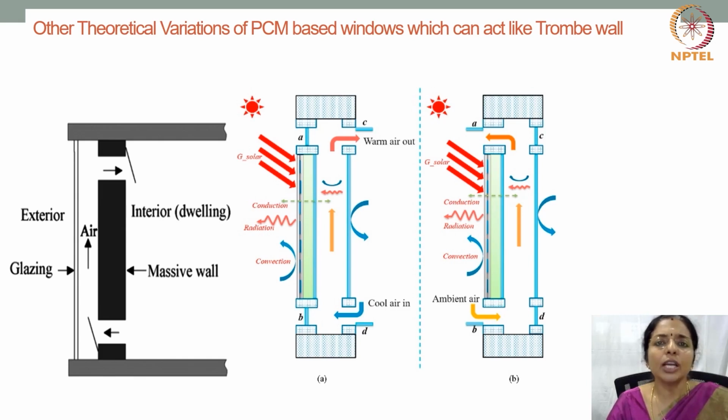The combination of trombe wall and solar photovoltaic panel is a viable combination to generate electricity and supply heat simultaneously. The thermal performance of a trombe wall depends primarily on its mass, since it stores sensible heat. More mass means more capacity to store solar energy and less temperature fluctuation.